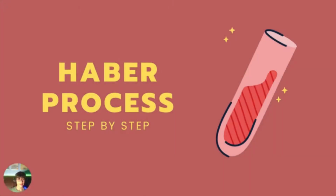Because this reaction is a reversible one, there will be unused hydrogen and nitrogen. So the unused hydrogen and nitrogen will stay gaseous throughout the whole process, mainly because they have a lower boiling point, and will be recycled back to the reactor. So to make this process easier to understand, I'm gonna explain it step by step. Let's start with the first step.